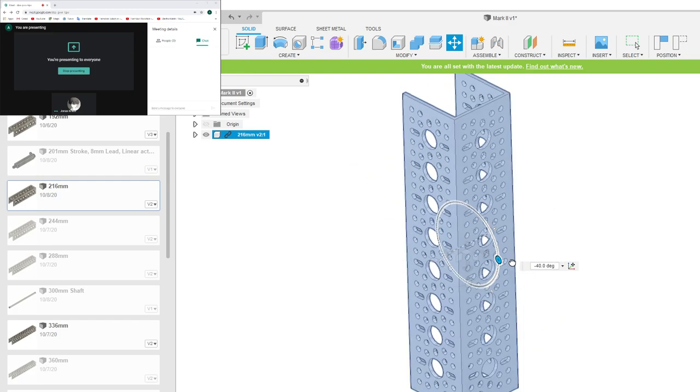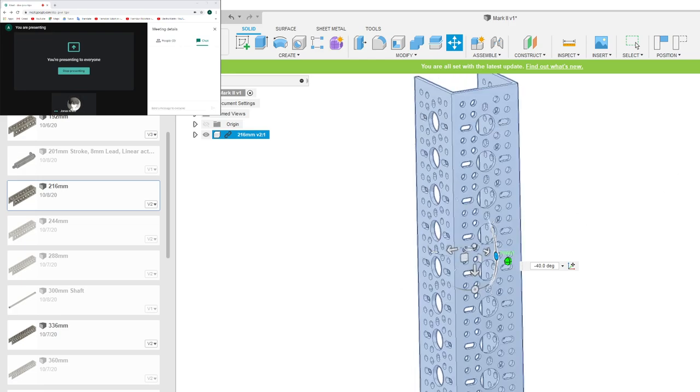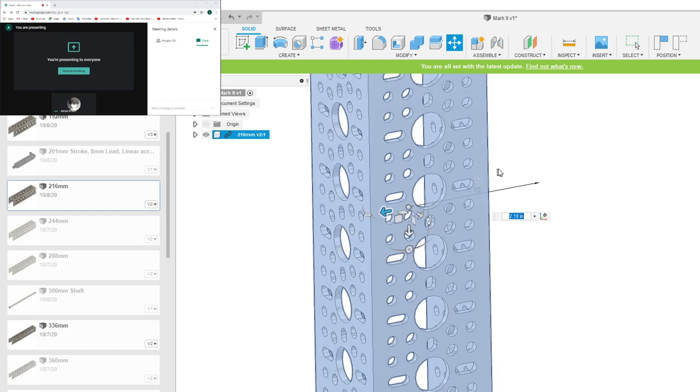Okay, so I don't remember what I put in, so it's going to be a little off. I hope that doesn't hurt anyone. Okay, so to move it, you just use these arrows and drag them back and forth. And you'll notice that it says inches. It depends what you're working with, and that is a major issue. When 3D printing something, your slicer has to have the same settings as this, otherwise it'll load weirdly. So I would not recommend that. I would recommend always having it in millimeters, especially because these pieces themselves are in millimeters.